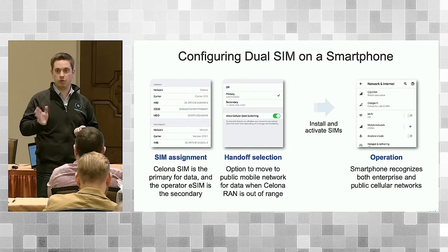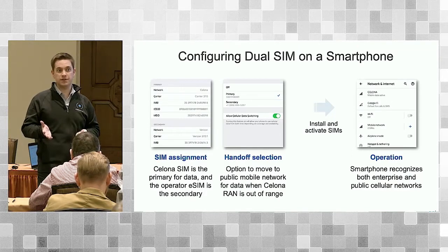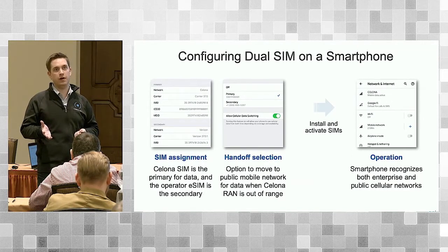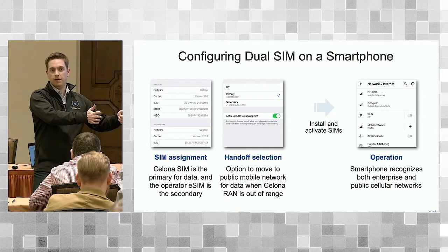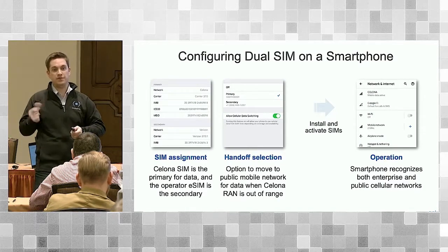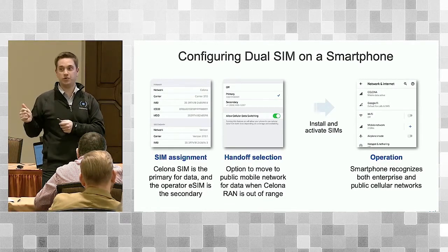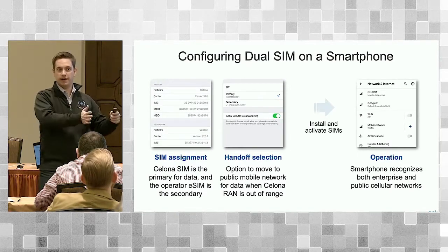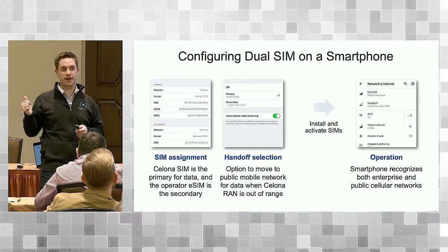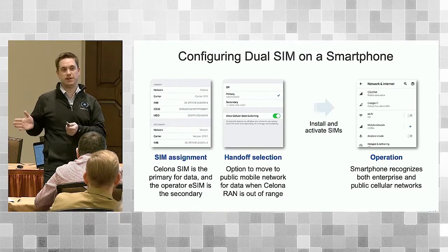selection algorithm of which one they connect to and when, because right now you will have a break in service. It's very interesting: if you're going from a secondary SIM operator into your primary, that transition happens very quickly, because when it sees the primary, it wants to switch to its primary right away. When you're going the reverse, primary to secondary, it tries to hold on to that primary for as long as it can. So sometimes you'll get a break before it finally times out and triggers to go to a secondary, because it wants to be more conservative and stick to the primary.